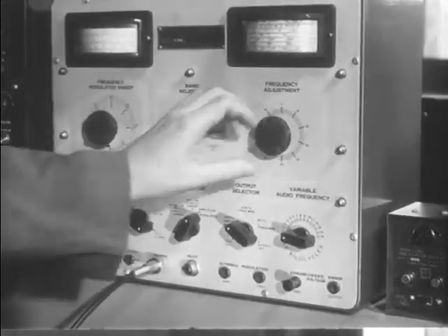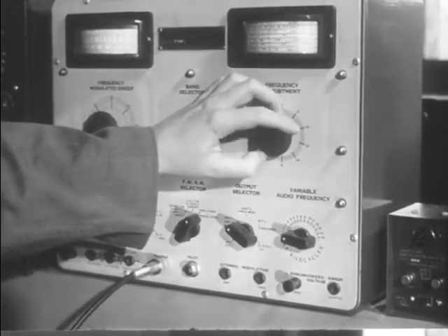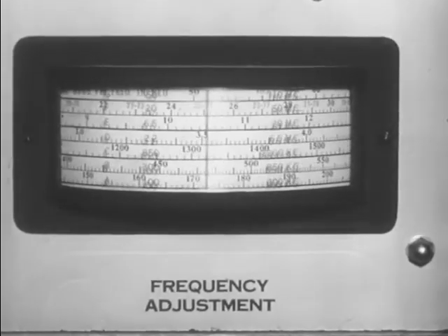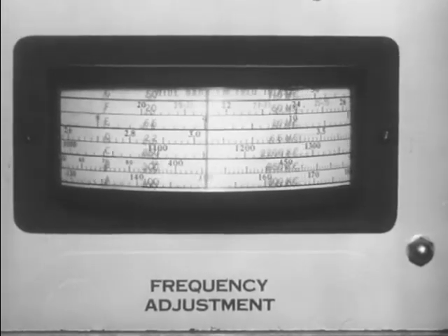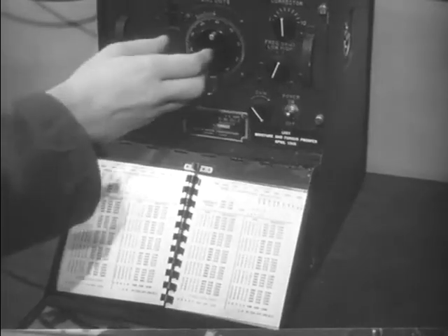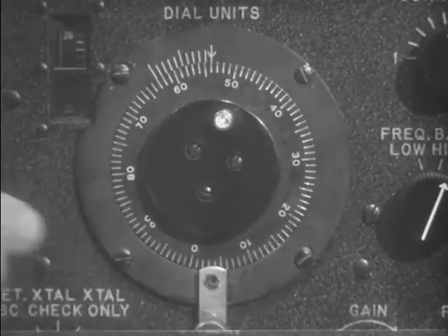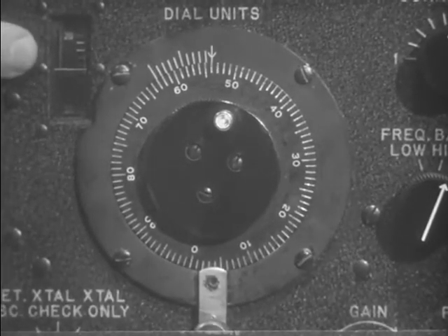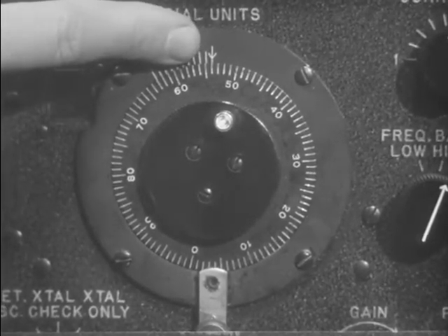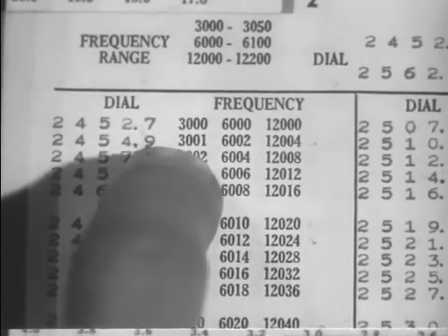The signal generator, through jarring or other mishap, may get out of alignment. A frequent check of the calibration of the signal generator with the frequency meter is advisable. It is only a matter of sending out a signal on the generator which is received by the meter. The frequency meter is tuned to the exact frequency until a 0 beat is reached. If the meter and generator dial readings agree, the generator is in tune.